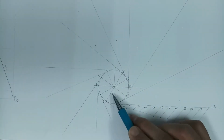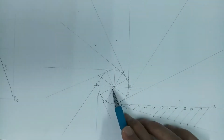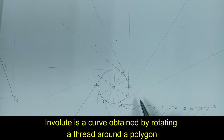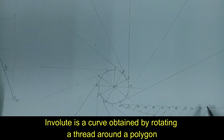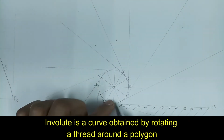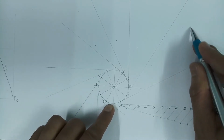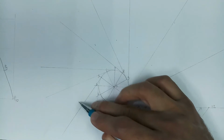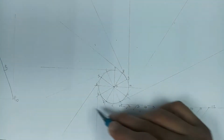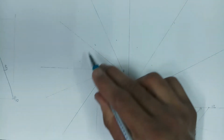As we see, I have drawn lines perpendicular to O2, O3, O4, then O5, O6 and so on. So this is the way all these perpendicular lines are drawn. Now if you know the basics of involute, involute is a curve obtained by rotating a thread around a circle and then unwinding it or winding it. Let us say I have got this thread which I am now going to start winding around this circle. Then as we see, this point will come close and finally it will meet at point 1. So the curve traced by that end point of the thread, or we can say string, is a locus which is called an involute.